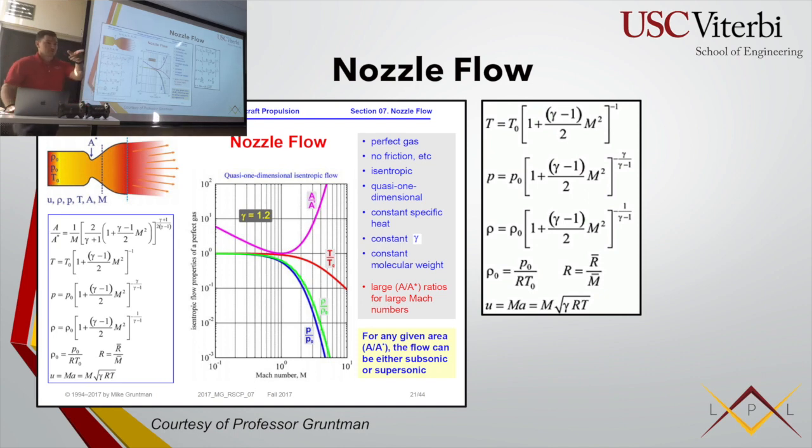So yeah, I imagine this has definitely already been looked into, but why don't you just have a sensor loop that detects the pressure inside of a variable nozzle, where you can change the... Yeah, so that's looked into, and that's kind of what the Aerospike does. It makes that always perfect, the Aerospike engine, if you ever looked it up. It's just really hard, because that means you always need to be changing your exit. You're talking about to P equals PA? Yeah, your exit always needs to be changing.